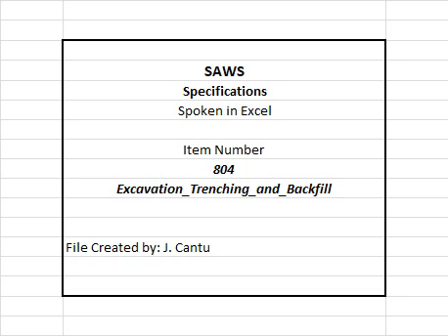6. Trench surface restoration. The surface of the backfilled trench shall be restored to match the previous existing conditions. This shall include final grading, placement of topsoil and seeding, placement of sod, such as at homes or businesses that had maintained grass, or other unprepared and prepared surfaces. Contractor shall compact trench and install an all-weather surface on any paved surface, roadway, or trench as directed by SAWS inspector, prior to proceeding to next section. Sections limited to 200 feet of open trench.